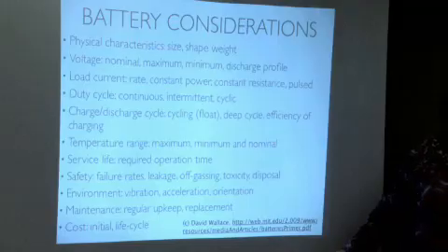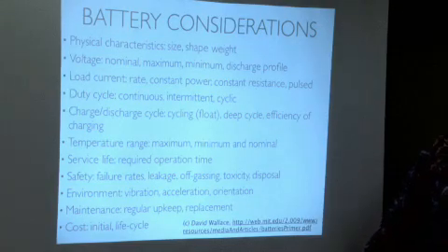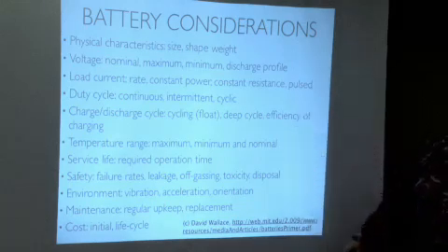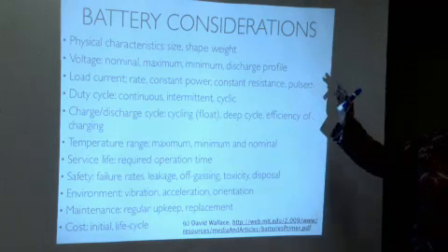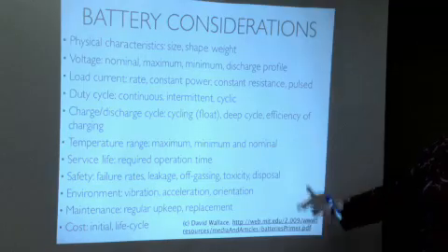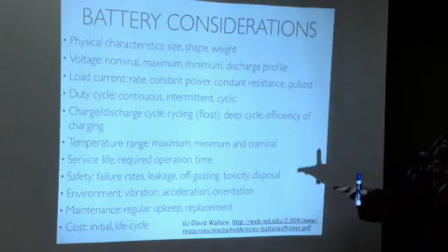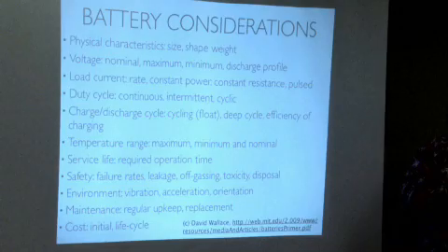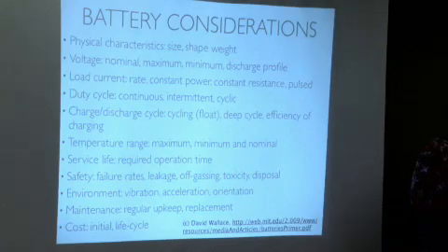We're really talking very simplistically, but when you really get into batteries, figuring out exactly what your peak load is, how much time you have, your current, it all matters, and it can get complicated. But the good thing is there are really great handbooks out there that explain it all. Batteries are really well documented. If you get a battery spec sheet, you see all the graphs, you can figure out exactly what you need. But you do have to realize going into it that you have to consider all these things, and you can't just grab a car battery and use it and expect it's going to work well.